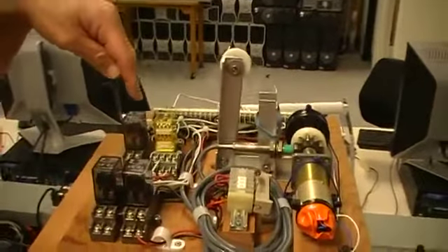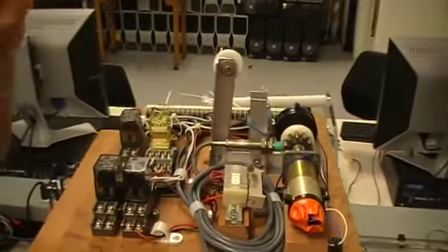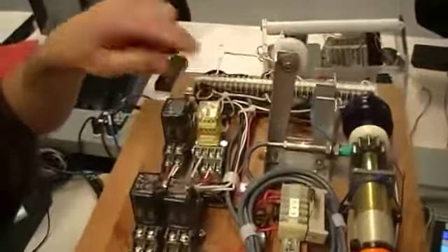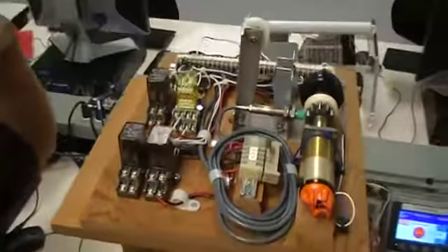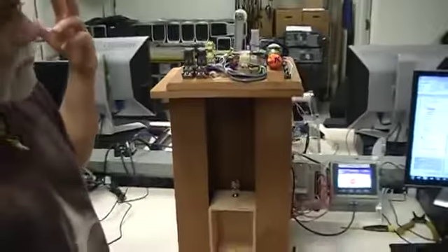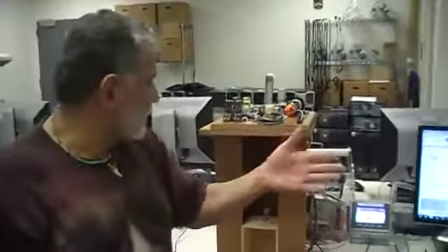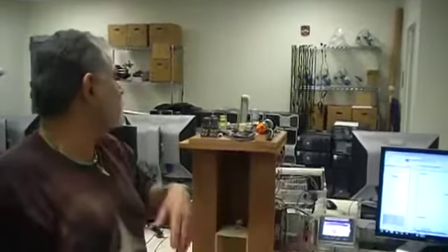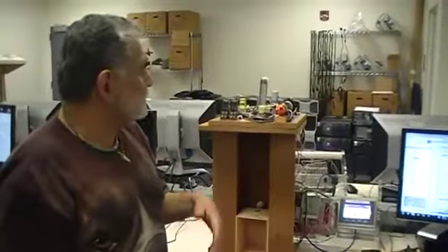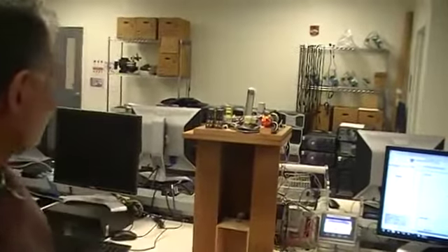Not only did I want it isolated and interlocked in logic, but also in hardwire, so that you'd have to have a double failure in order for this thing to run away. That's the redundancy when you're moving people around in equipment. That's one of the things you have to look at all the time: triple redundancy, sometimes quadruple redundancy, depending on how critical the system is.